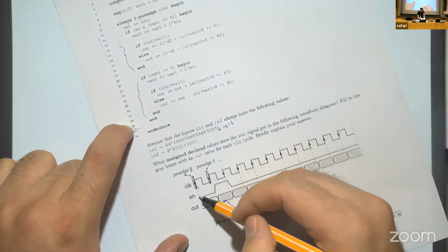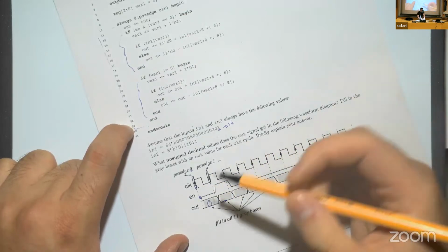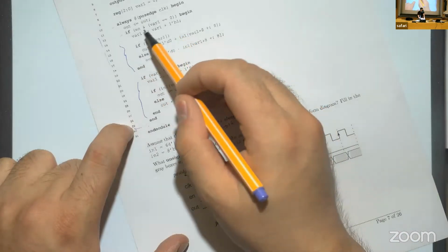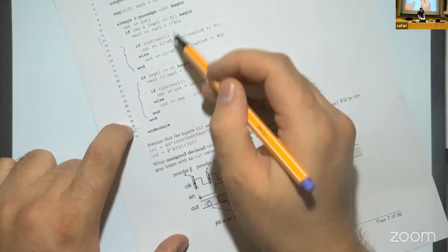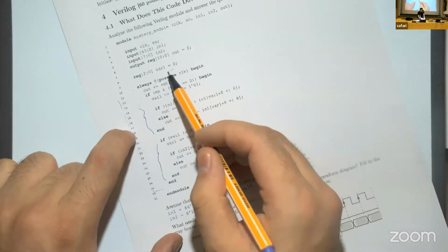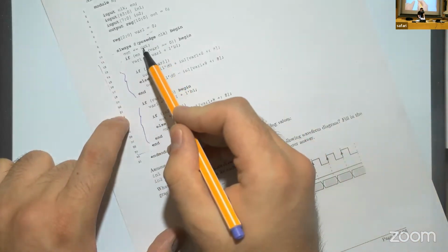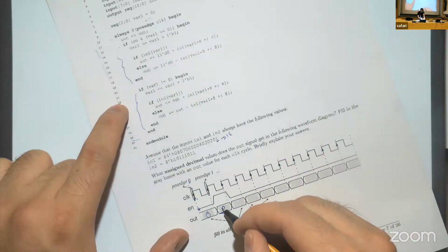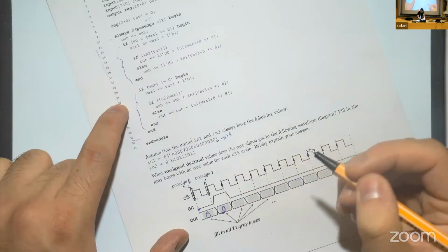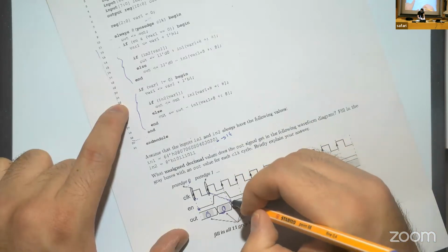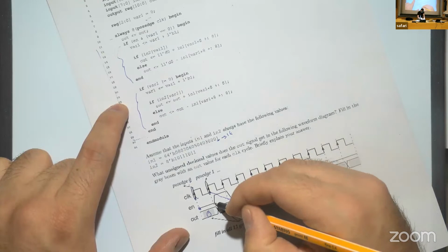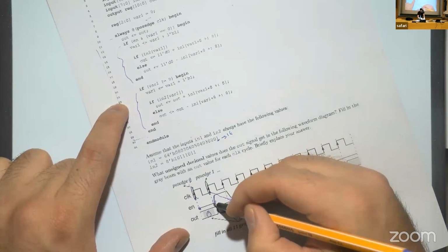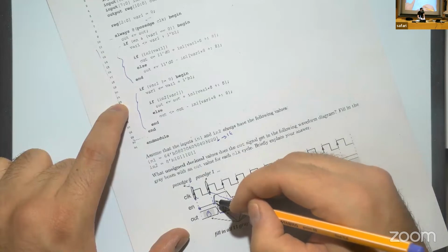Here, out will be updated using this one. We see that enable is 0, so we go to this if clause. Enable is 0, so we cannot satisfy this one, and variable 1 is initially 1 here. That makes the output again have the same value as the previous one, which is 0. This posedge clock 1 will affect this one. Here we see that enable has risen, so enable becomes 1.